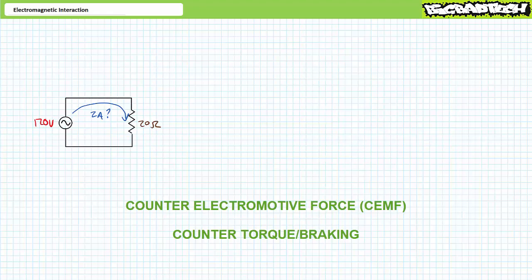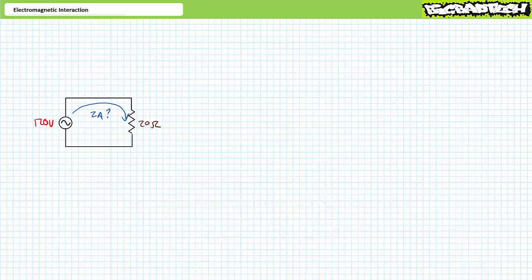Let's examine Counter-Electromotive Force first. As you are no doubt aware, the interaction of magnetism and electricity creates movement. This is motor action as defined by Fleming's left-hand motor rule. My question to you is this: why does a motor winding with an at-rest resistance of, let's say, 20 ohms only draw 2 amps when operated at its rated speed when energized by a 120 volt source?